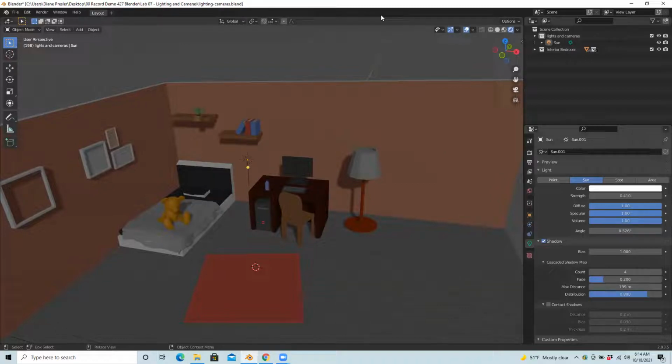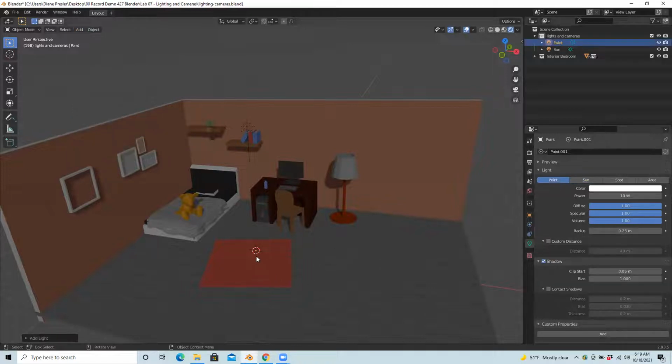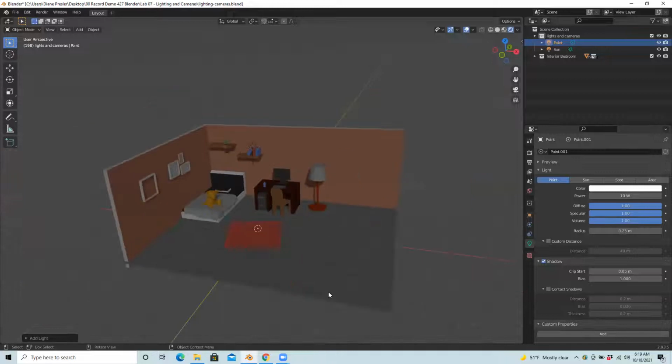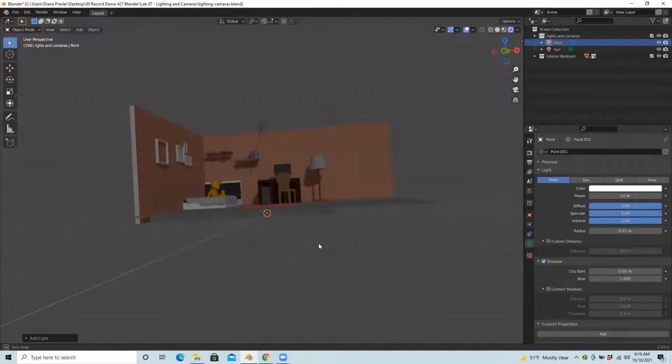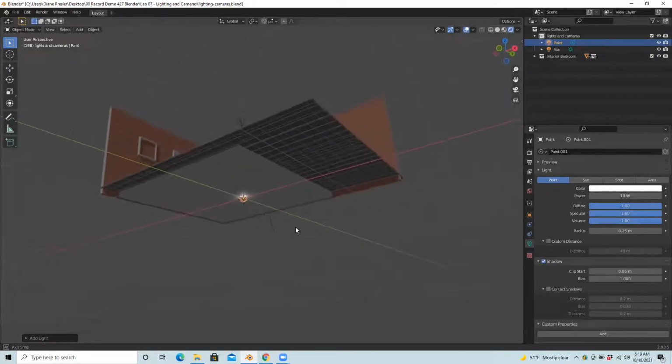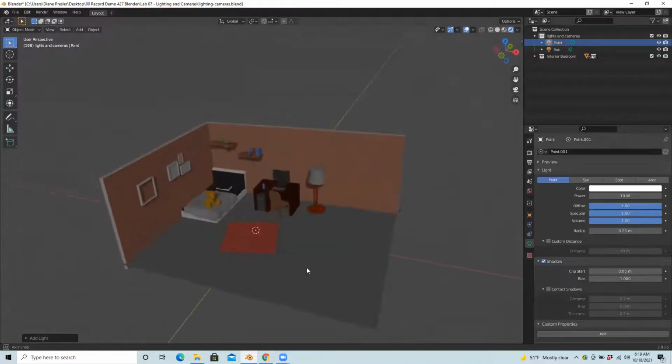The next step is we'll start to add more lights. So I'm going to go over to the add menu, light, and let's try an additional light. This time I'm going to choose point light and try to simulate something like an overhead light bulb. Let's choose point. And by the way, I think it actually dropped under the floor. The first time I dropped this in on the scene, I thought, I don't see the light. What's happening? But weirdly, the floor is a little bit above the point of origin. It looks funny, but the light is in the basement. It's under the floor. Let's just move it up higher.